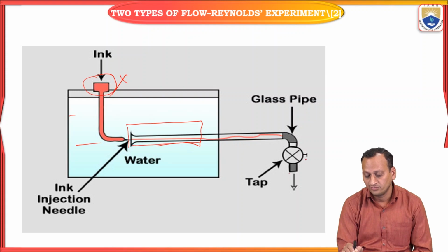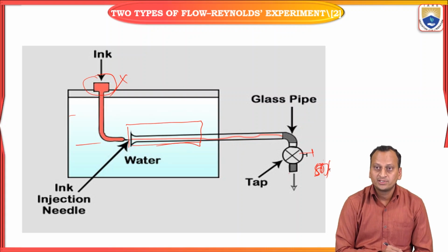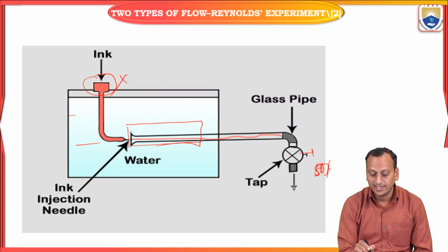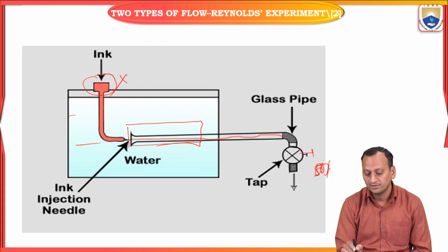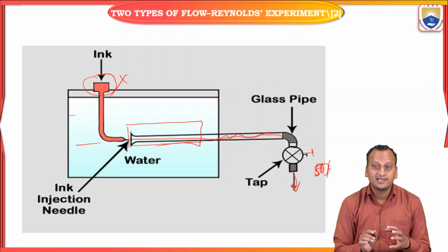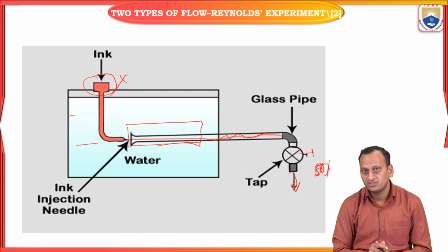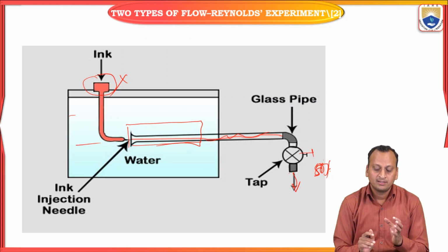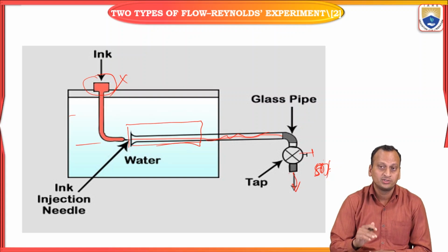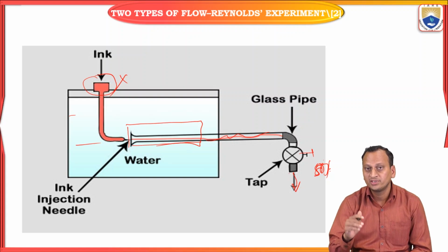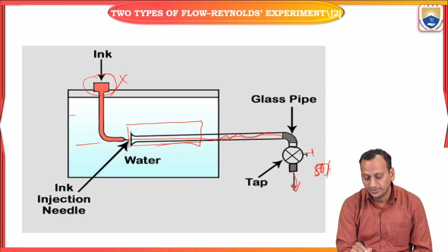Whenever the valve is opened further, if it is open to 50%, then gradually the velocity of the liquid will be increasing. As the velocity increases, the fluid particles or fluid layers may not be stable. Gradually they will go from laminar, they are going to be disturbed, and they are going to transform into another zone. Therefore it becomes a wavy one.